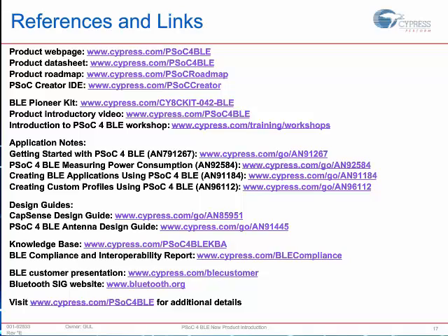The system can be used as a BLE device, but can it also act as a central device and essentially scan for other BLE devices? Absolutely. So once you drag and drop the BLE component in your PSoC Creator schematic, you can pick and choose how you want your BLE GAP or GATT configured.